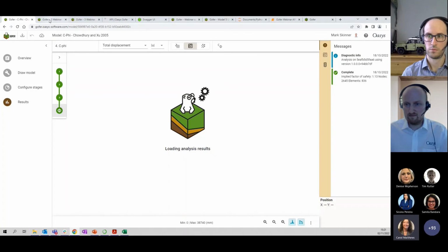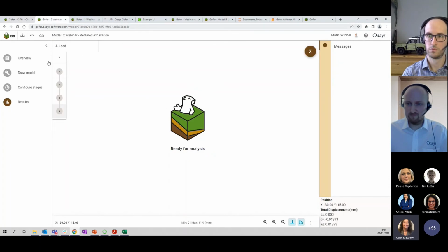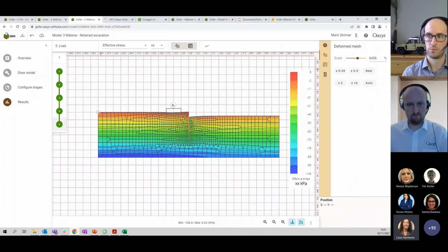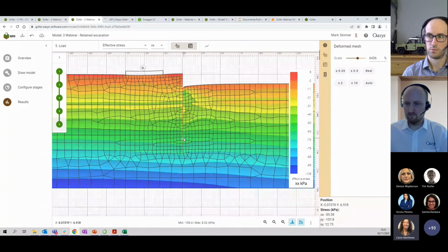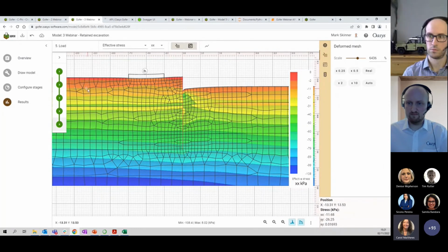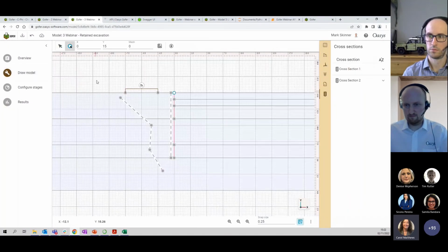So yeah, this is the same sort of question as the previous one about the mesh density. You can set the mesh density at any node, and you can also select groups of nodes. When Mark showed moving nodes in groups, you can do the same thing. You can select a group of nodes and amend the mesh size on all that selected group at the same time. So you can edit things pretty much however you like as far as mesh refinement goes.